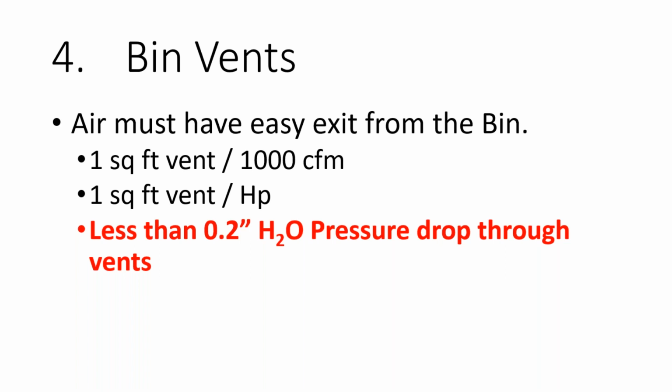So with our IBD monitor, you can set this and have an alert sent out if it gets above your set point. For the most part, I haven't seen too many bins with poor vents or poor venting. The real area where I do see some concerns is wind blowing lids shut and your vents freezing up if you're drying with significant condensation. But it is important to be aware of and to monitor that aspect of it.